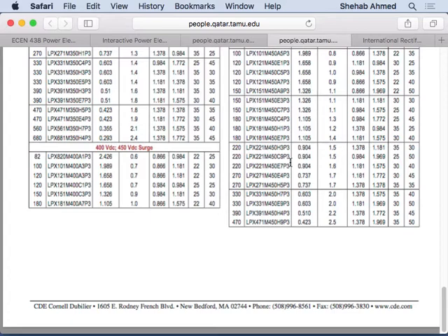Then you have to size the capacitor to make sure that you are... That means the minimum ESR you can have gives a minimum voltage ripple of 2 volts at that current. That's assuming you have an infinite capacitance, which means there is no ripple contribution due to the capacitance. So with infinite capacitance, you still have a 2 volt ripple. That's huge. That's a significant amount.